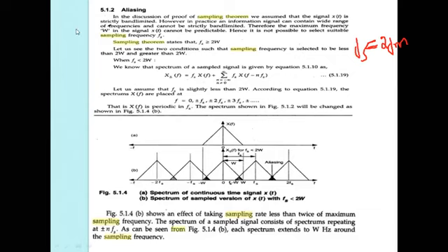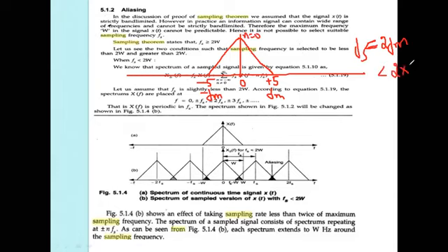If I use a waveform, the same example we took for the greater than and less than cases, with plus 5, 0 and minus 5, that is Fm and minus Fm, it is band limited to Fm hertz when n is equal to 0. Now I am assuming that Fm is equal to 5, so 2 into 5 is 10, and Fs is less than 10. Now you can assume a value less than 10, so Fs is equal to 8.